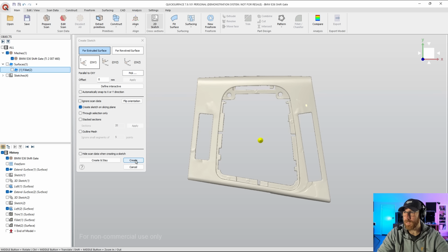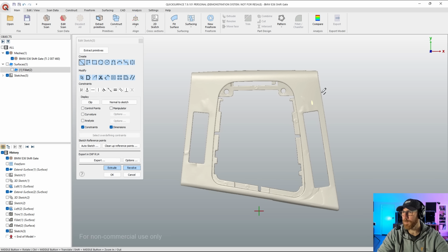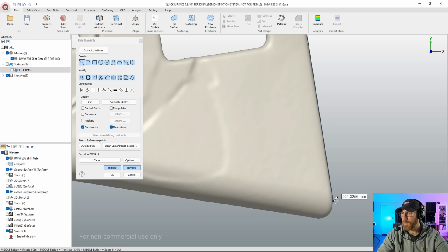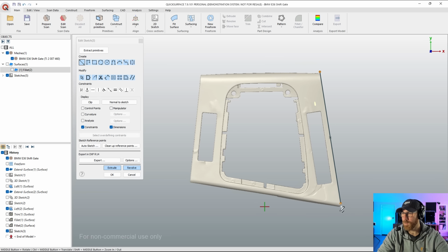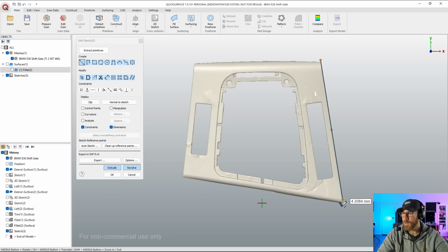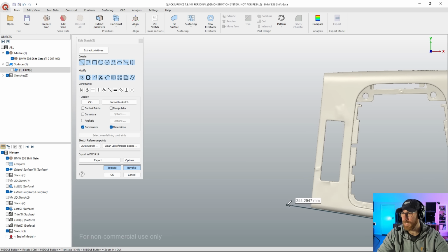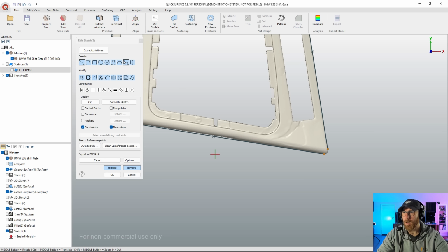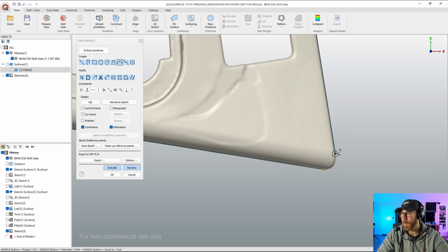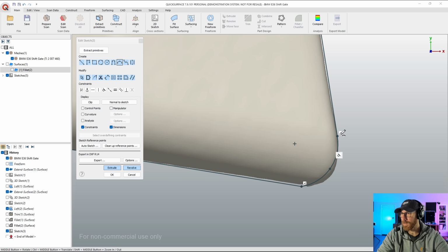What I'm going to do is basically come in with a straight line, and this corner gets rounded, so it needs to have an arc there. I'm going to come back and do that arc after the fact, but I'm going to go, let's say, from here. I don't really need to trim this part, but I do need to trim this left side. So again, we're going to come in here, get it kind of close enough. I'll come back with an arc. So I want it to be essentially tangent at this intersection.